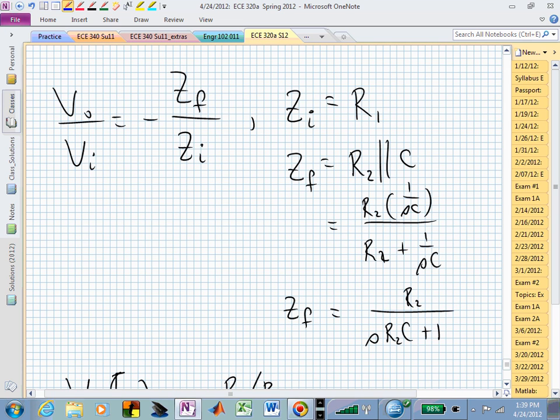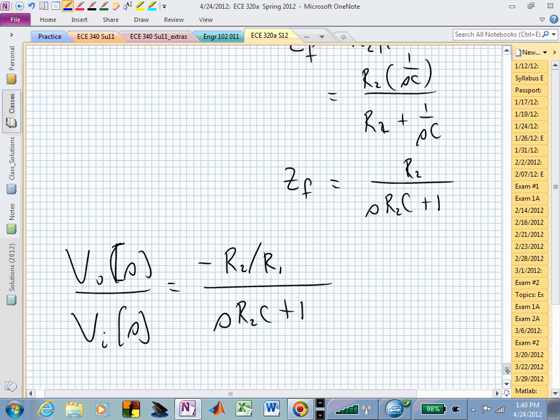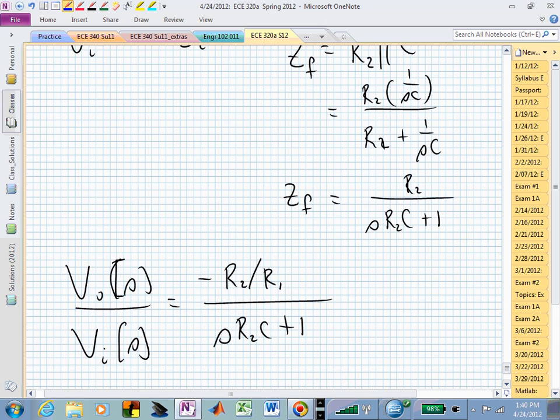Now hopefully you can see that I have this, well, what's my DC gain? It's hidden. But now my DC gain from that is minus R2 over R1. Well, what if you wanted a positive gain? You could put another inverter, either on the output or the input of this circuit. You may want that for buffering purposes anyway. So we're not going to worry about that.